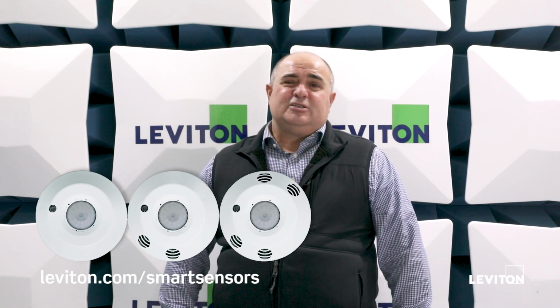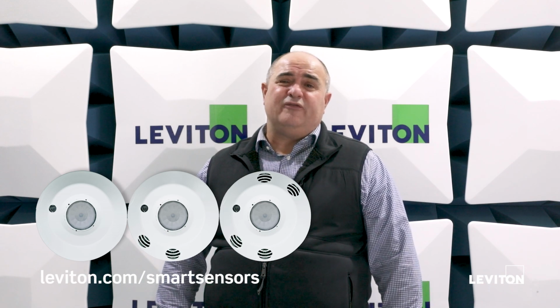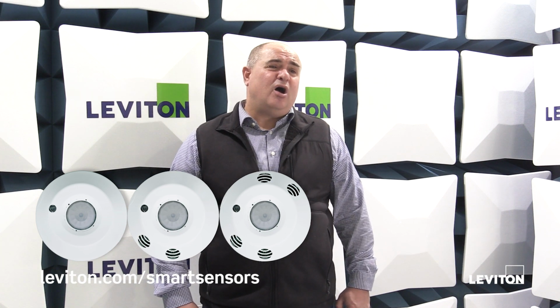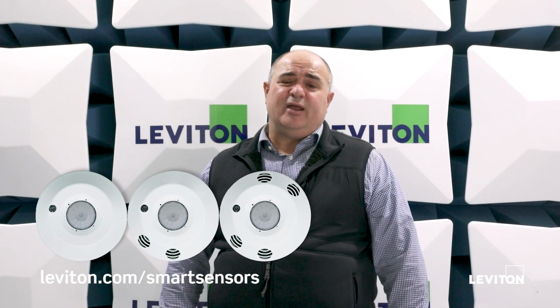And with the sensor technology, just keep in mind with all of these solutions, especially the multi-tech, if I'm wanting it to be passive infrared only and I've installed the multi-tech version, I can in fact turn off the microphonic, or if I only want it microphonic only, I can in fact turn off the passive infrared.